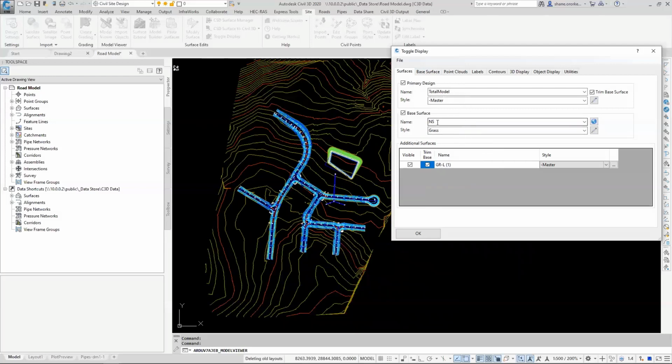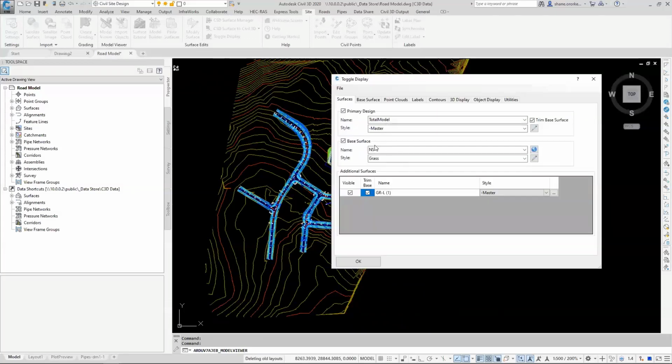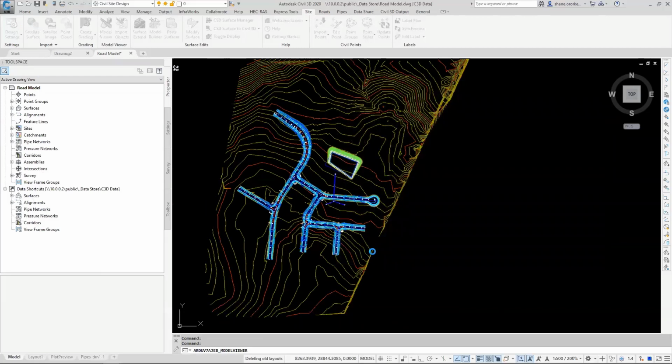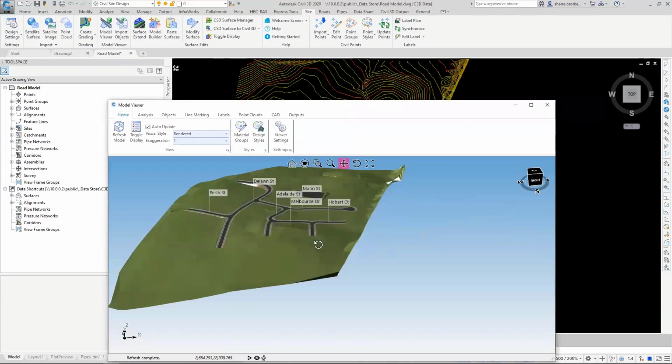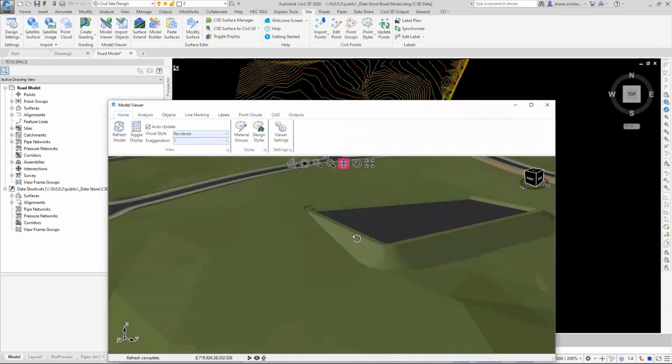Well, the NS surface, and I've got Model Viewer. I've started Model Viewer. I can see every Civil 3D surface, whether it's come through a data shortcut or not. I can also see every civil site design surface, whether it's come from my drawing or through a data share. So in terms of surfaces, everything that's in the drawing, however it got here, is available to me to use. Fantastic. Okay. Now, it'd be interesting to see with the NS whether or not that actually displays, but only because that question has come. Oh no, there you go. Well, there's the answer. Fantastic.